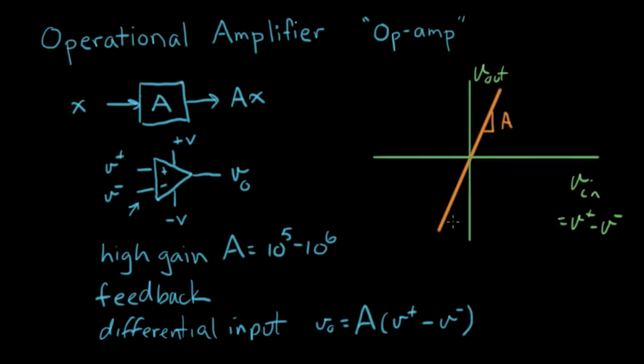very, very vertical. Now, one of the properties of this is that V out cannot go above or below its power supply voltages. So on this plot here, that's called saturation. If V out gets up to V plus, we say it saturates and looks like this. It goes flat basically here and here, where this voltage value here is minus the power supply, and this voltage right here is the positive power supply. But over this range in here, between those 2 points, it's quite linear. It goes through 0, and this is where we use it most of the time.